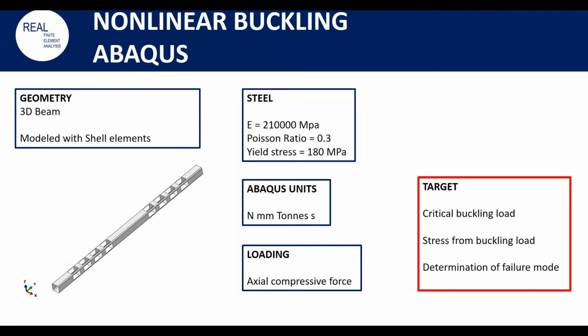The loading will be an axial compressive force, and the target of this analysis will be to get the critical buckling load, the stresses from the buckling load, and we need to determine what is the failure mode. That is, if the beam will fail under buckling or just under the compressive load.